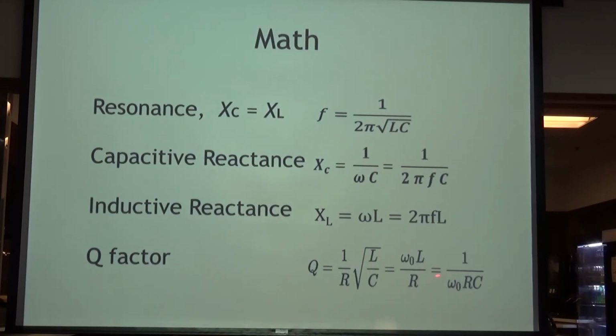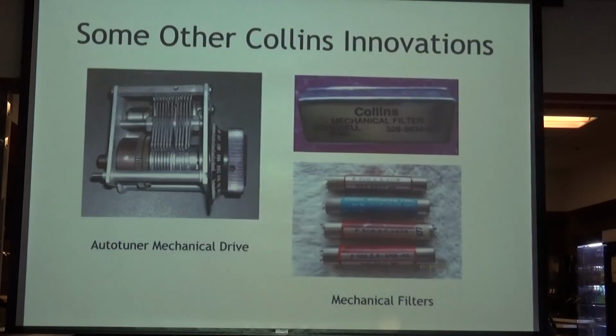And then Q factor over here, I'm not going to spend a lot of time on this, but originally the inductor was the culprit for lowering Q because it had all this wire in it, and that added resistance. When you went to a tuning capacitor, the dielectric, now being air, caused what's called an equivalent series resistance to occur, which actually was higher than the effect that the inductor gave you. So you had a lower Q factor. There are things they did to improve the Q factor in capacitor tuners, but you got it kind of automatically in the PTO and in the inductor tuner.